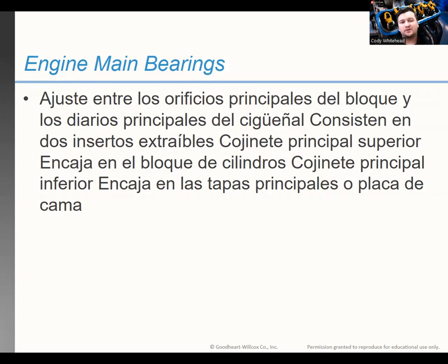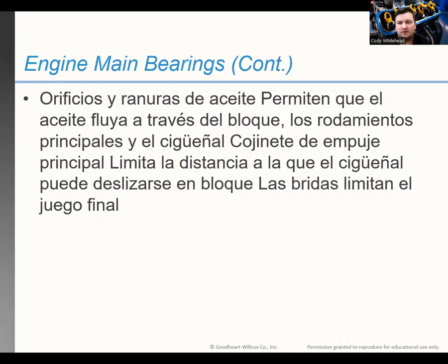That's why motor oil is so important. That's why the viscosity is so important. The thickness of oil is dependent on how much of a gap there is between the crankshaft and the main bearing. If it's a bigger gap, we need a thicker oil. If it's a smaller gap, we need a thinner oil. Otherwise, that oil isn't going to create a good film, and the crankshaft is going to hit that bearing and cause damage and premature wear.